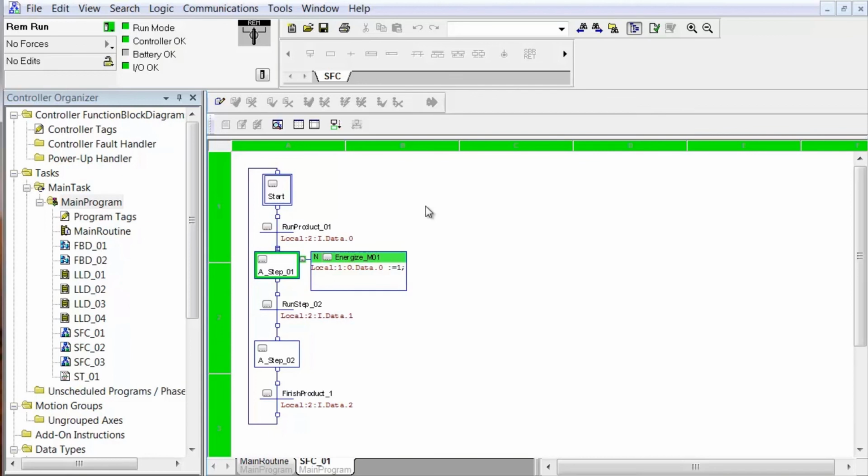Turn on that output. So does output 0 ever de-energize anywhere within this routine? Does it de-energize anywhere in the whole sequential function chart? Now ignore the fact that there are other routines using the same I/O tags, albeit they are not executed per the JSR instructions in the main routine. Although these bits are used in other routines, we're not executing those other routines.